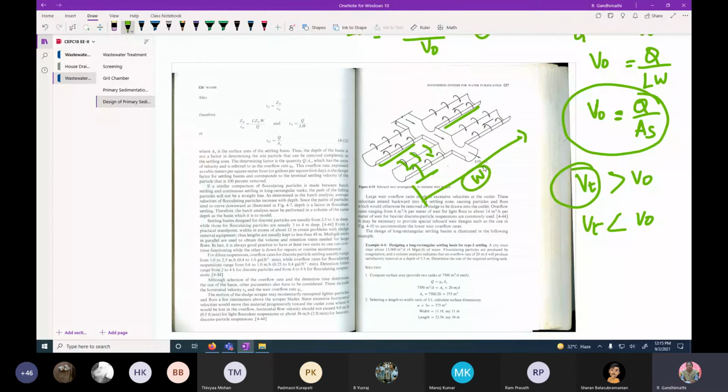That means initially it is W. Now it is entering the system W plus W. Is it clear? This is called weir length. Now you can see here it is not only W. It is entering these narrow channels from two sides. Therefore, for one channel alone, the weir length is W plus W. Then here you have one more provision, so W plus W again. Is it clear?